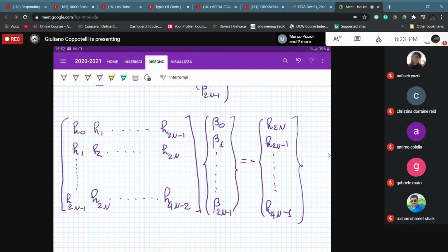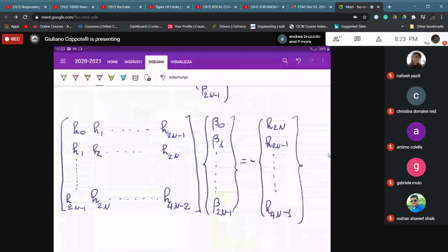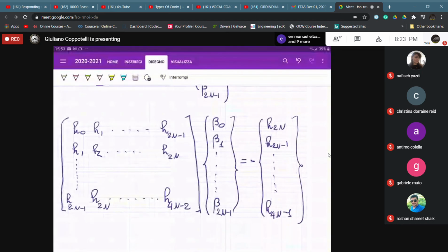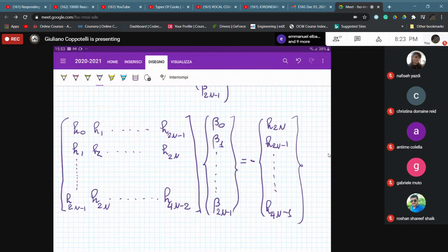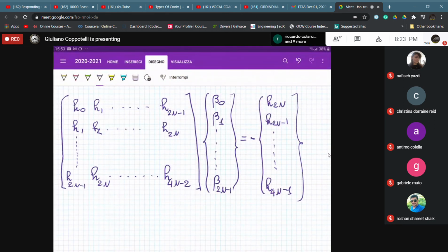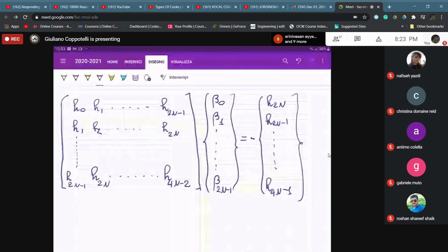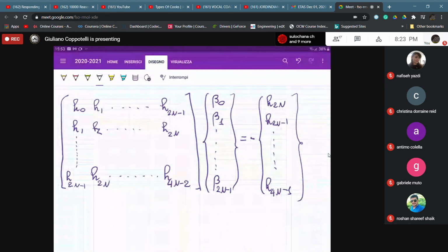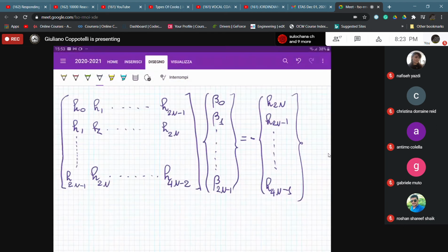And remember, we made the inverse Fourier transform of the FRF in order to have these H coefficients. Also, the right-hand side, that is the vector of the known terms, is known because all the coefficients are the same impulse response functions that are already available once we know the FRF. So the only unknowns in this equation are just the coefficients beta. And then we are all set. Then we are very happy. We can party all night long because we have a way of evaluating these unknown coefficients.